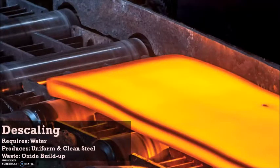The descaling process. The heat treatment process produces an oxide scale buildup, which is a waste, which the descaling process will remove. This waste is removed by various ways. The most common way is using water or the pickling processes. The pickling processes present hazards to the workers and facilities due to the acids used, but we will be talking about this more later on.